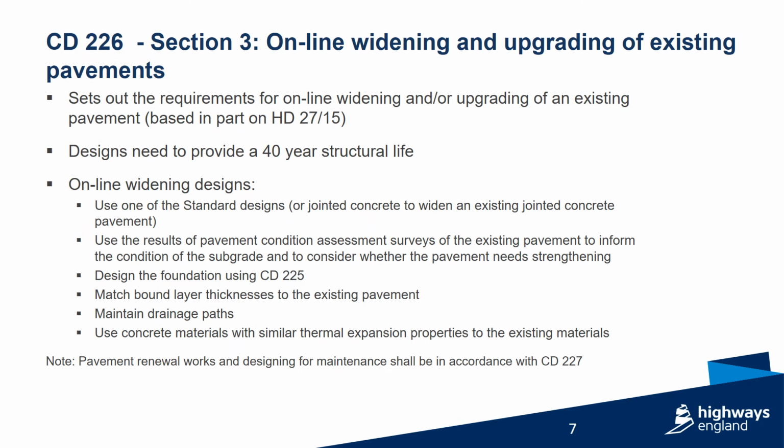Section 3. Online widening and upgrading of existing pavements. This section sets out the requirements for online widening and/or upgrading of an existing pavement. This is based in part on HD 27/15. Upgrading of an existing pavement includes conversion of a hard shoulder to a running lane and incorporation of an existing pavement into new construction.